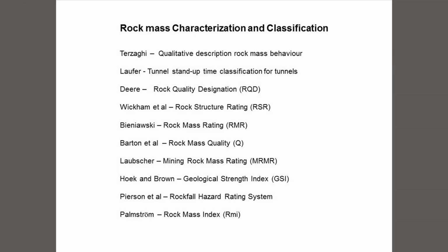So when you stand back from that and you consider building a tunnel or a slope in that, it almost looks like a homogeneous rock mass, like a sandy soil with very big grains. And so in the early days, we were able to do quite a lot of work by assuming that rock masses were homogeneous, uniform in their behavior. And this then led to the evolution of a number of classifications. Remember, we're still talking about the days when computers weren't available. We're still looking for techniques for gathering and interpreting information that have to be rather simplistic in their nature.